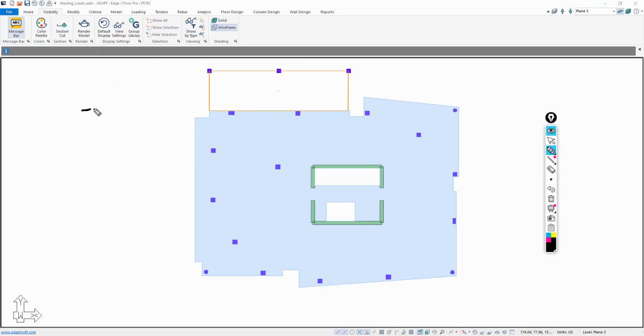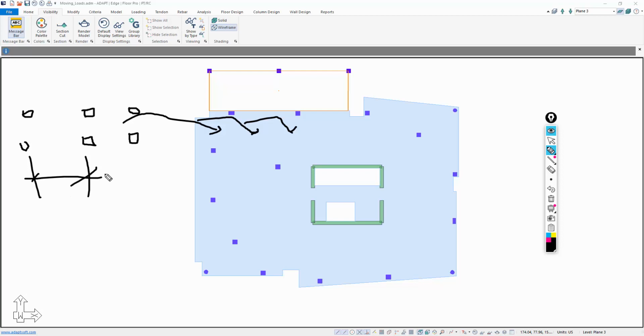Let's say we have four loads, and these could be represented as small area loads, basically a patch load, by some grouping like so. So this grouping I want to be able to place here, maybe move it here, and maybe I have this positioned in 20 different locations on this slab. This grouping could be an axle or an engine, let's say, with an axle in the back, similar to some AASHTO HS20 type loading where you have some distance here and then another distance here.